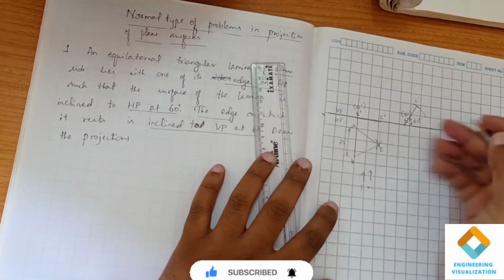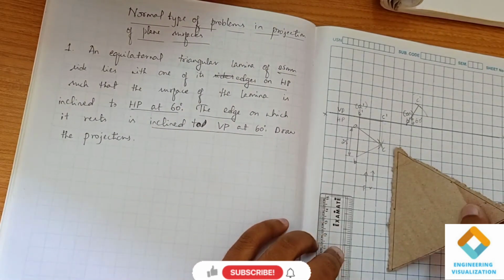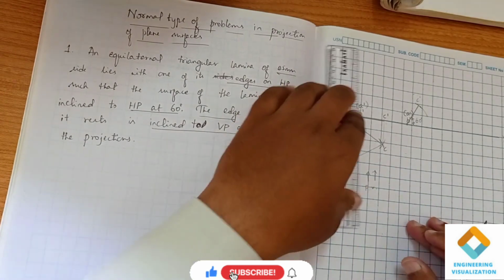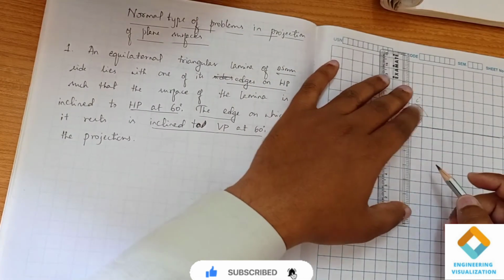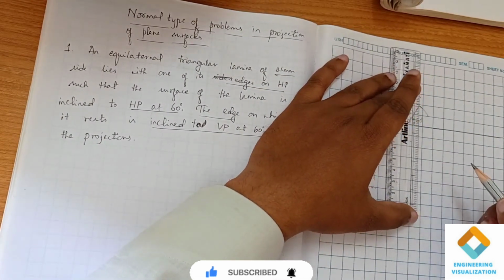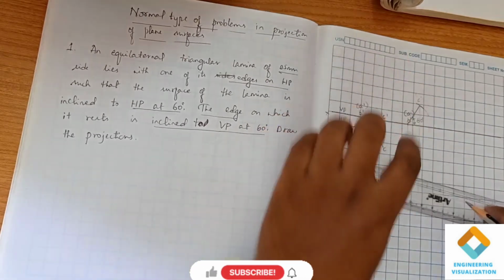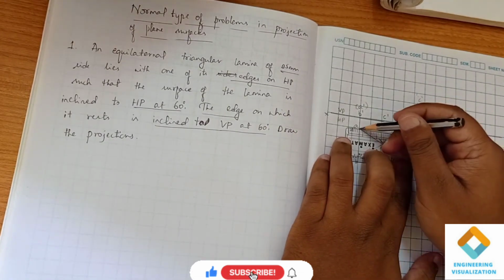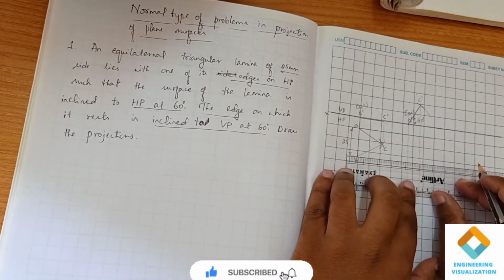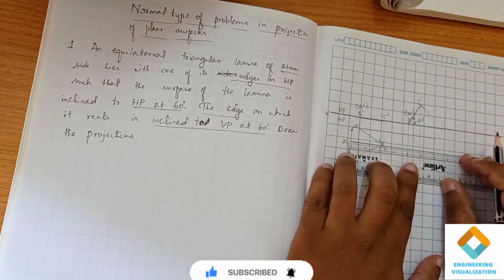Now we have to draw the inclined top view. Say this is inclined at 60 degrees like this, so we have to draw the top view of it. How do we do that? Using the projection principle. You just follow the procedure and you will understand. Projecting the lines downward, from both the front view and top view on either side, we can construct the second position inclined top view.